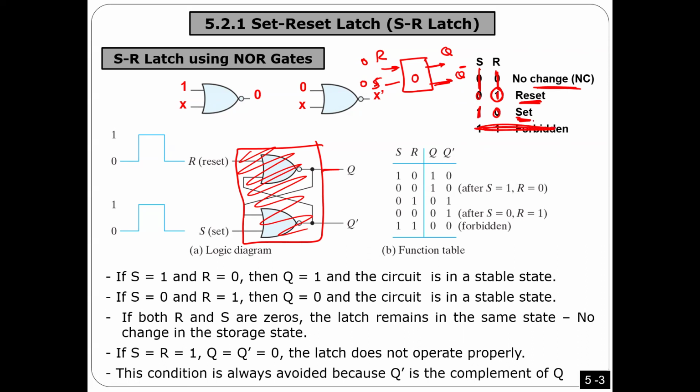Okay, so conclusion, this is like a big picture before I give you the details. I have a latch, we call it SR-latch. This can store only 1 bit. This is the stored bit here, we call it Q, okay? And you have the inversion of the stored value. That's why these 2 outputs should always be inversions of each other. They must be. If this is 0, this should be 1. If this is 1, it should be 0. Must. Okay? Anyway, also, the way it works is here, we have 2 inputs.